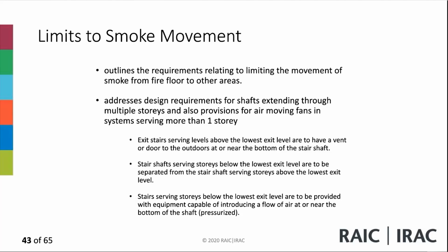The stairs serving the upper levels need to be vented at the bottom of the stair shaft. You need to separate them from the stair shafts below, and you need to provide pressurization for stairs serving levels below the exit level.